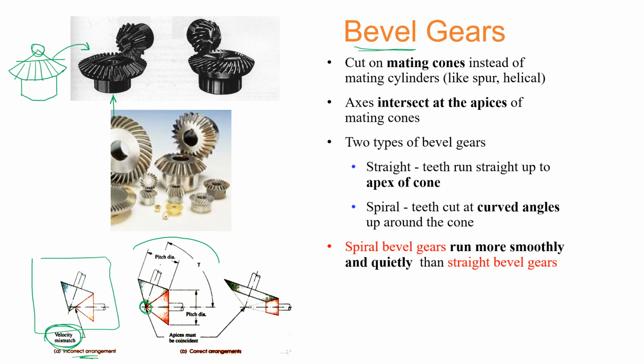Now, the other thing that you can observe is that the input side and the output side are spaced apart with this angular displacement gamma. And that's exactly because of the angle of these bevel gears. This is the good thing that we may exploit while using bevel gears, that you can have the input side and the output side spaced apart at different angles.